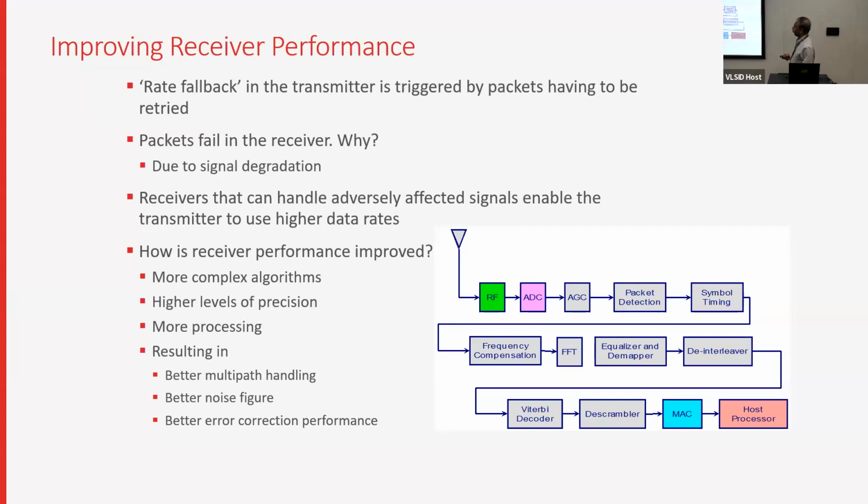Everything comes at a cost, remember. You can process more. That means you can have a Viterbi decoder which can go to greater depth. You can do lots of processing in the receiver at a cost of the size of the circuit increasing, but eventually you can get gains. You can optimize for multipath. For example, in Bluetooth, normally everything is line of sight because of the distance.